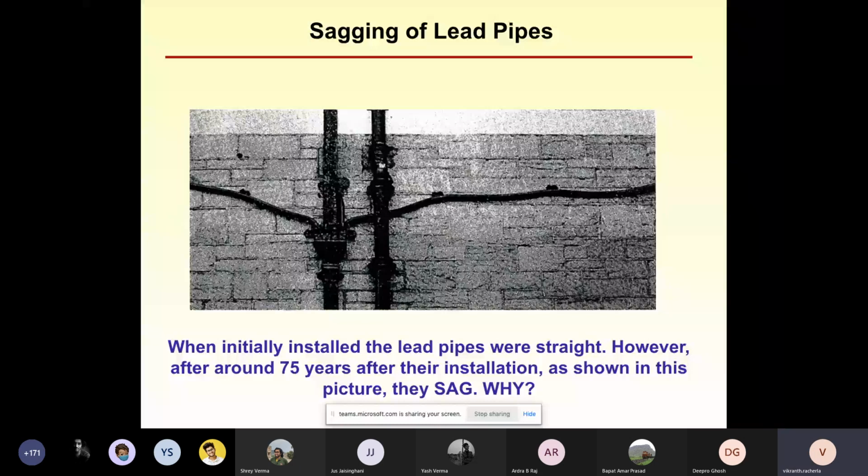And in power plants, all power plants, particularly nuclear power plants, and that too these thorium reactors, I don't know how many of you have heard or read about it. Over there they are planning to use liquid sodium in order to do the heat exchange, so the operating temperatures are high. Basically, wherever operating temperatures are high, you have to pay particular attention to creep.